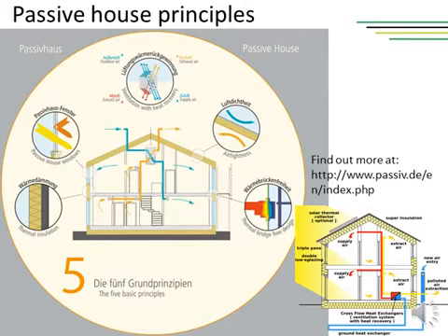Passive house standard is one of the standards to achieve very low energy consumption for maintaining a comfortable indoor climate. Here are basic principles of this kind of design. It employs continuous insulation through its entire envelope without any thermal bridging. You could hear more about thermal bridges in a previous lecture. The building envelope is extremely airtight, preventing infiltration of outside air and loss of conditioned air.